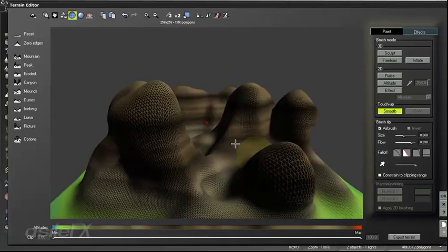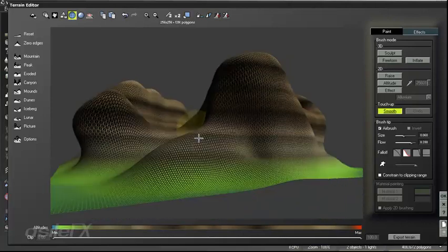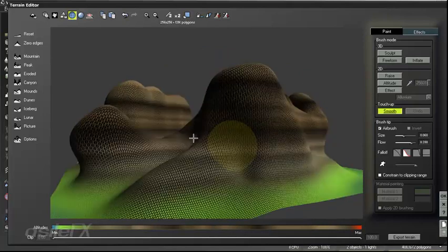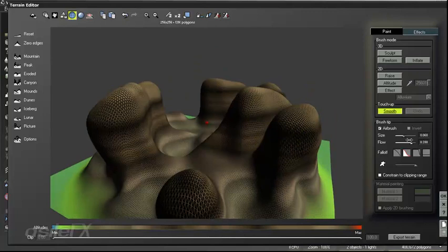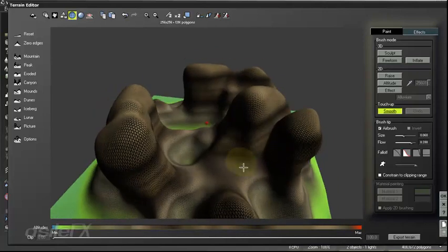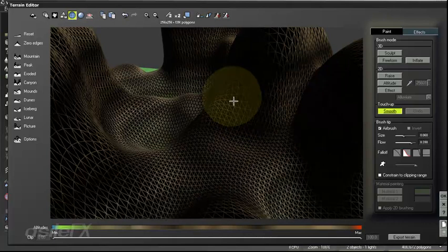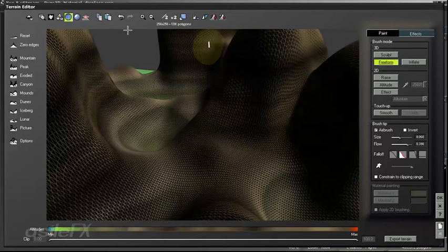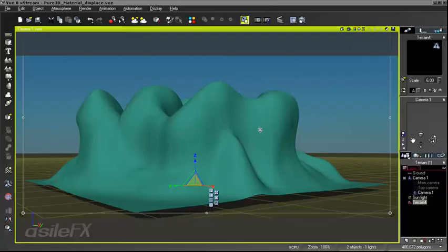And because we have so much vertical geometry now, I do want to start thinking about subdividing or reducing the brush size and increasing the overall displacement geometry in order to give us a little better of a mesh. So before I do that, I'm going to save out the scene and then subdivide the geometry, because once it's subdivided and the displacement geometry is increased on the terrain, we will not be able to undo that action.